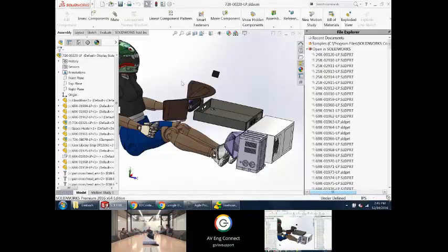The plus on that is that like in your EPDM system, it's not going to be looking for that extra file. The minus on it is that if that assembly ever gets corrupted or saved wrong or whatever and disappears, that part disappears with it too. That subassembly would disappear. The components themselves would still be okay because they actually were files, but the subassembly only exists in that assembly. So if that assembly ever has a problem with it, that part goes away too. So pluses and minuses, doing it either way. Okay.